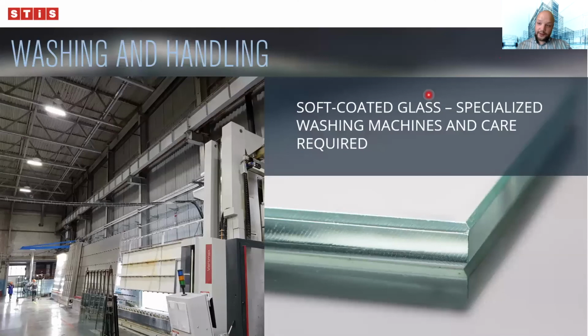Special care should be taken when washing and handling the soft-coated glass. Special washing machines, special gloves, special care and training of your employees is absolutely required. But again, most of the processing companies already know it and already know how to work with the soft-coated glass.